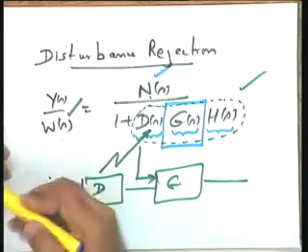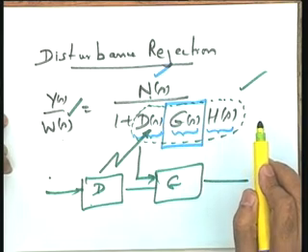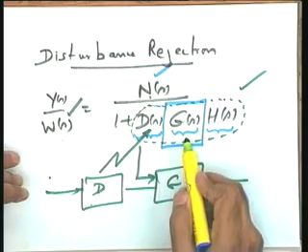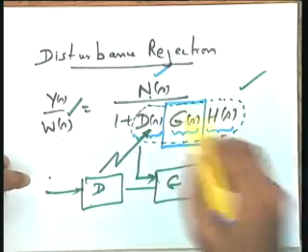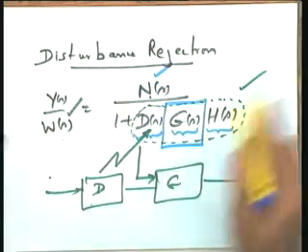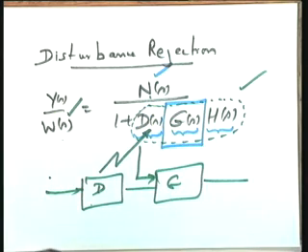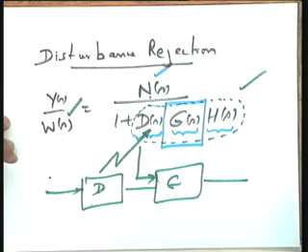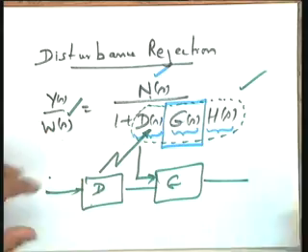So it means, you see that, just don't go by this blind rule that increase of the loop gain will improve the disturbance or will reject the disturbance. How is the loop gain being increased? That is also important. If you increase the loop gain through G, there is a possibility that you are increasing the gain of N, and if you are increasing the gain of N, you are causing problems for the system rather than taking away the problems or finding the solutions to the problems. So this is all a complex situation, you see. It does not go in a sequential way that you increase the loop gain and it will reject the disturbances. You have to account for the total system in totality and see what are the parameters which are getting affected by change in gain of any of the components.